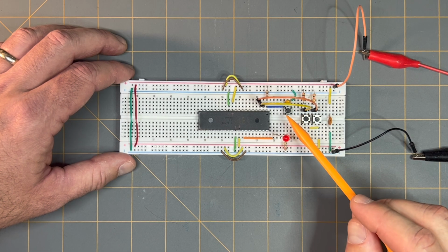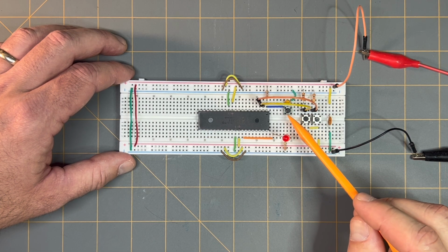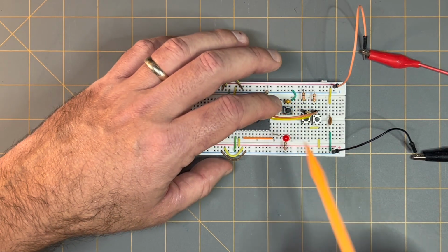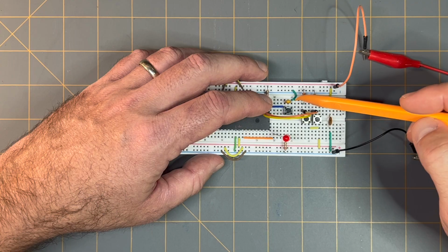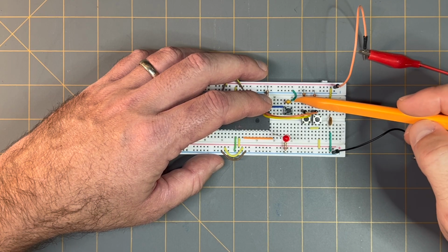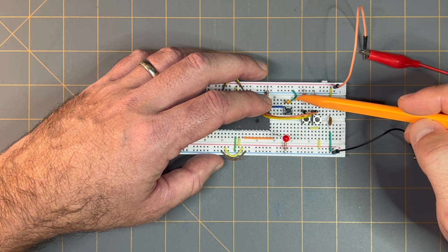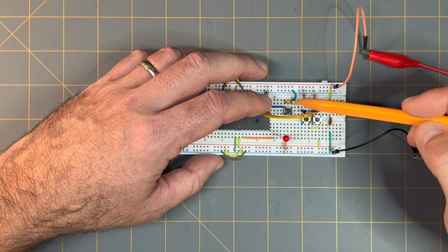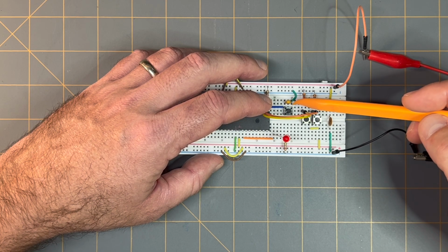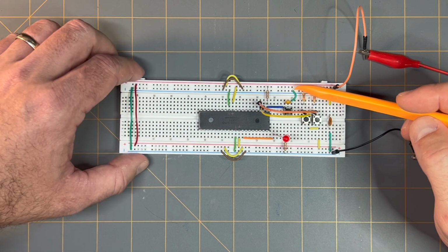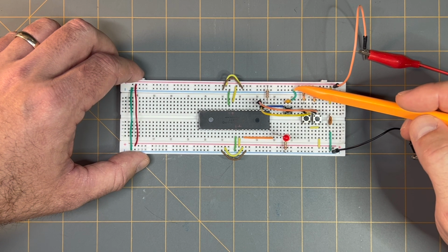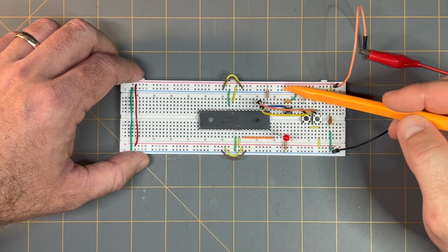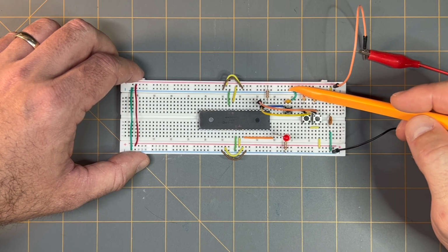B15. To complete the connection for the reset button, I took a green jumper wire right here and placed one of its terminals in point A15 in line with the capacitor and the switch's terminals on the same row. And then I placed the other lead or leg of that little green jumper wire into an adjacent point along the negative power rail of the breadboard.